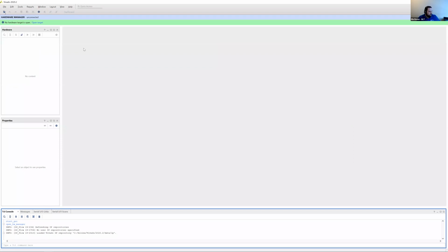So the next thing I want to show is my hardware. Sitting next to me, and I'm going to switch my camera, I have a ZCU104 evaluation board. This evaluation board has a 7EV part that contains the video codec engines. It has a slot for external DDR memory, a slot for M.2 memory, HDMI ports, a DisplayPort, Ethernet ports, some PMOD, as well as an FMC expansion header.